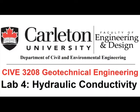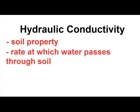This is a tutorial for the Hydraulic Conductivity Lab of the Geotechnical Engineering course Civ E 3208. The purpose of this lab is to determine the hydraulic conductivity of a soil sample. Hydraulic conductivity is a property of the soil which determines the rate water will pass through it.